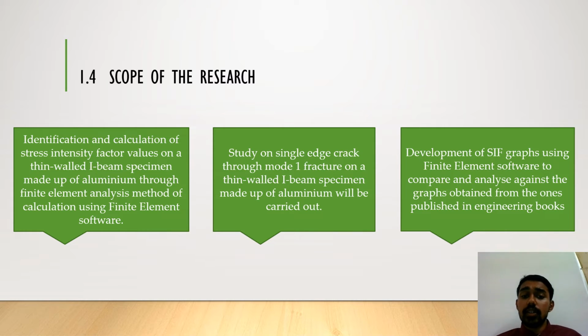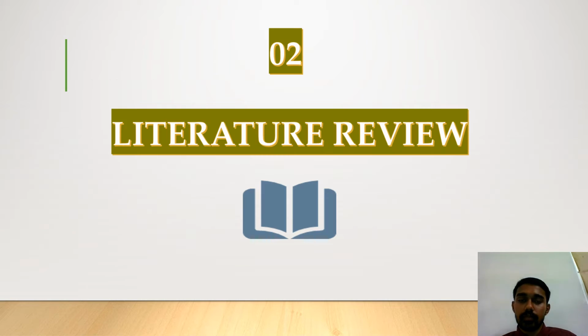The second one is to study a single edge crack through mode 1 fracture on a thin wall I-beam specimen made up of aluminium. The last one, development of SIF graphs using finite element software to compare and analyse against the graphs published in engineering books.